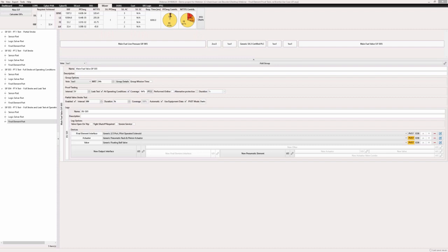For example, if you have a burner system and you have many different scenarios where every action is close the valve, why would you be closing the valve every time? You can simply test if the valve operates once and take credit for it in all the other functions. So a more segregated proof test could be beneficial from an overall maintenance requirement perspective, but also better on your equipment.